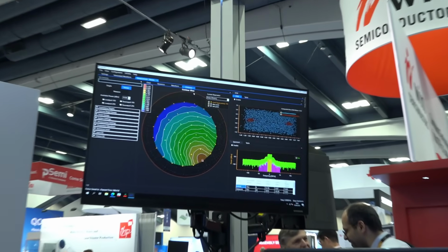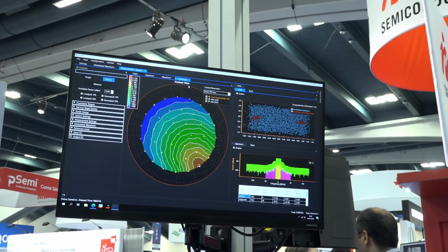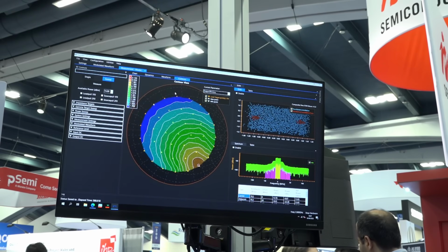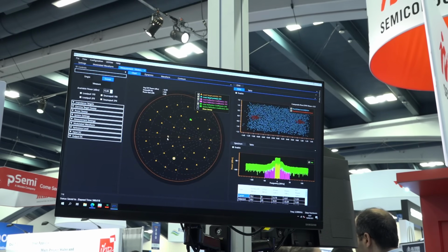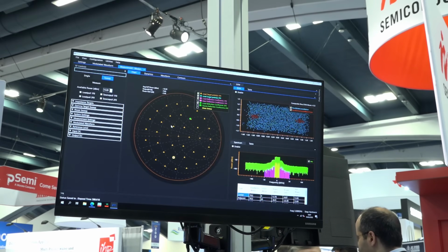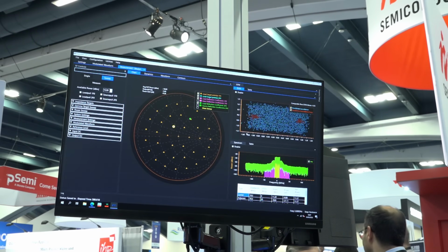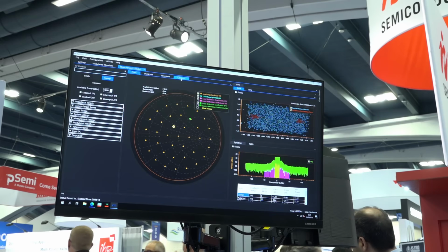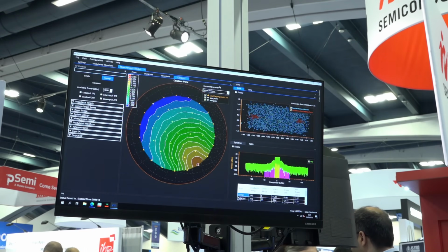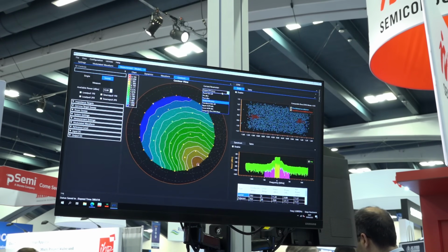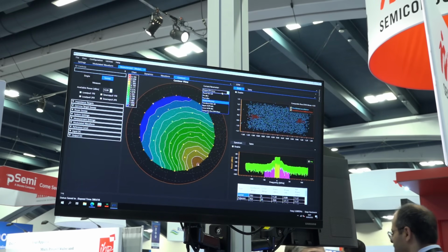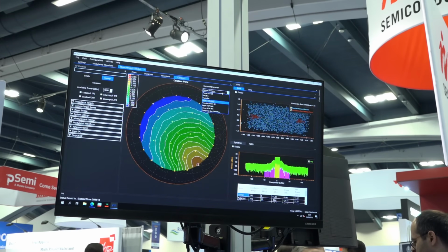So to give you an example of what kind of data they generate, it's really quite impressive because there's a tremendous amount of computation that's happening here. So here's the Smith chart space, all the different individual points. You select all the individual points. You see the waveform exactly at every instance. You can go to the second harmonics and look at that. And then you can plot all these contours. And these contours will give you, for example, an EVM contour across the load pull. So you see where you get the best EVM from this particular Wi-Fi amplifier.